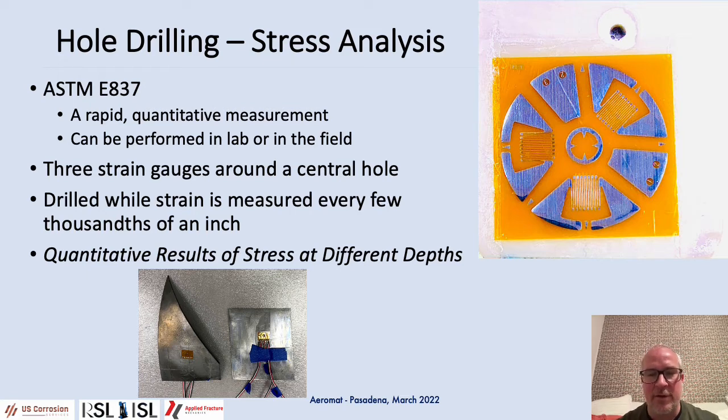And once you record enough data, you can take that and use the equations provided in the ASTM method to calculate quantitative numbers for the stress at different depths. And this can be really helpful because then you can see whether the material is under tensile or compressive stress, or if there are shear stresses there. And then all of that data can be put into models so that you can more accurately understand what's going on when a failure occurs.